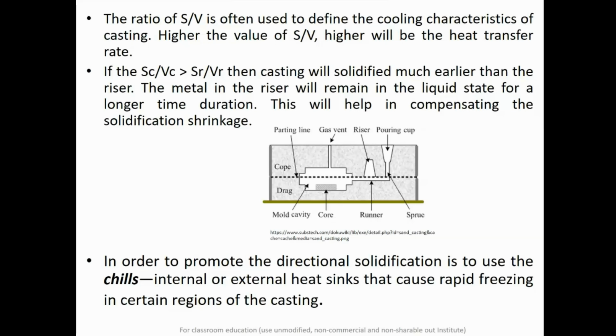Somewhere I told you that it is very important to design the riser, because if it is not carefully designed, then definitely you will have these types of solidification shrinkage defects observed in the casting.